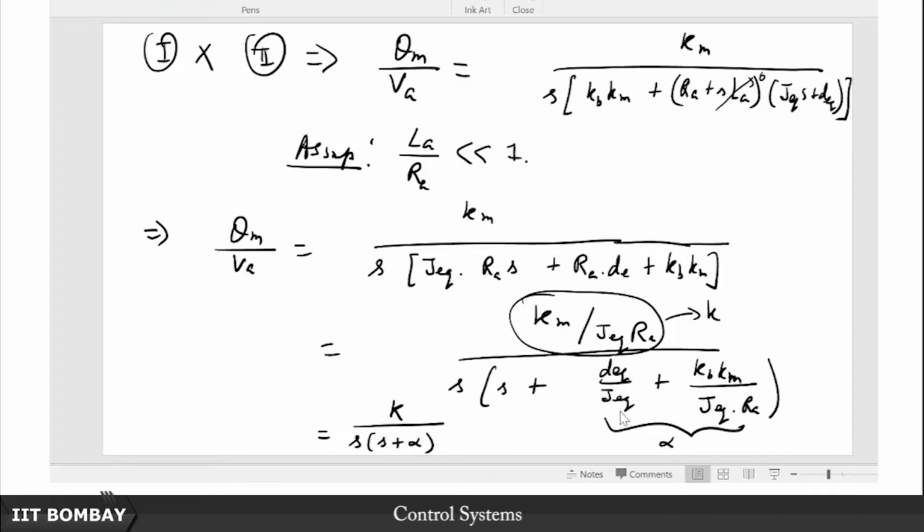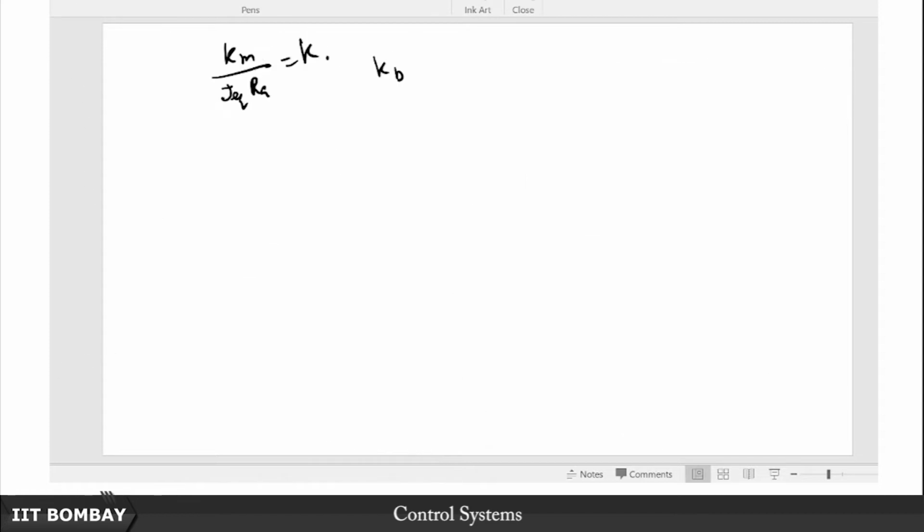Of course, these I can measure mechanically by a dynamometer experiment, or they can be calculated from the mechanical knowledge of the mechanical system. But at least from the electrical side, how am I to determine these? Another observation here is, of course, you have Vas is equal to Kb times omega S plus Ra times, of course, we have assumed that this inductance has been already ignored.